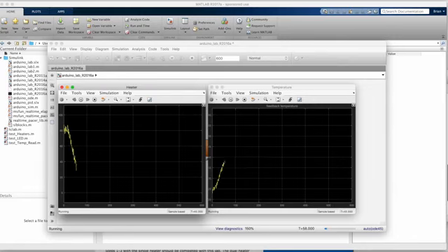First, the heater set point on the left is no longer jumping between a max and min value, but is being set to a continuous set of values. High at first when we want the temperature to rise quickly, and then lower as it reaches its desired temperature. Now, there's still an overshoot, which means I don't have it tuned very well. I could probably increase the D term to remove the overshoot. However, there's something else that I want you to notice.